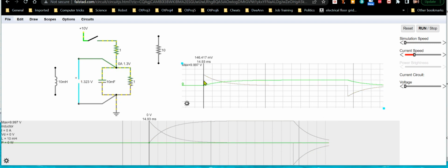But see here, basically you've got an external source of power. That's what's causing it to charge. And here, it's the capacitor that's discharging through a load. In this case, there's an external source, 10 volts applied through the switch, that's charging the capacitor. Here, the capacitor itself is actually the source of power because the switch has been disconnected. So the only direction current can flow is around in a circle here. But at first, the current is flowing through here, as you saw when I didn't have this resistor on.